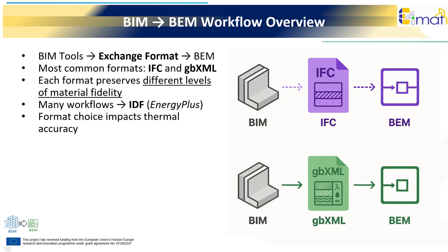Depending on which export path the BIM model takes, the resulting BEM model may retain more or less of the original thermophysical detail. Most workflows eventually produce an IDF file for EnergyPlus, where all material data must be explicit and numerically complete. Understanding that different routes into IDF offer different levels of material fidelity helps manufacturers anticipate where their properties may remain intact and where they may require additional support or guidance.